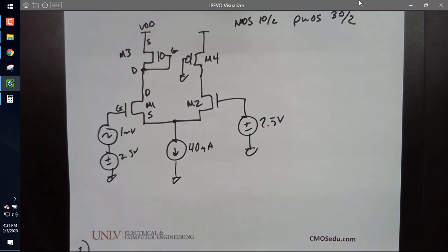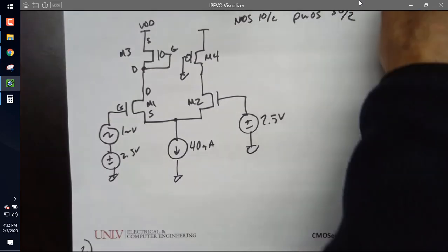All right, so I want to go through, and first, whenever you're in analog design, the first thing you do is the DC biasing. Why do we do that first? You need to know what's in saturation, what's in triode, and once I know that, then I calculate the small signal parameters. This problem is very similar to what I put on a PhD qualifying exam in electronics, because it goes through basically everything. Okay? So let's use orange to write DC.